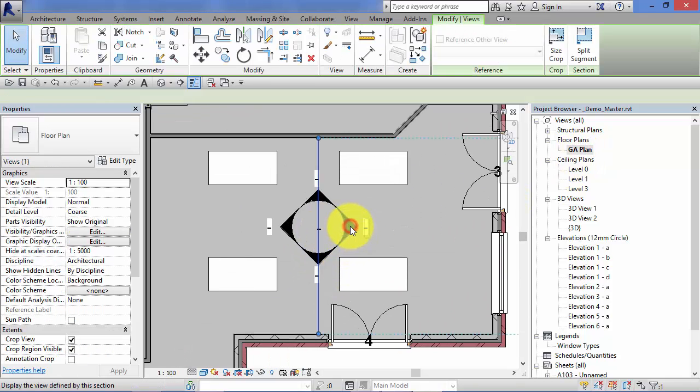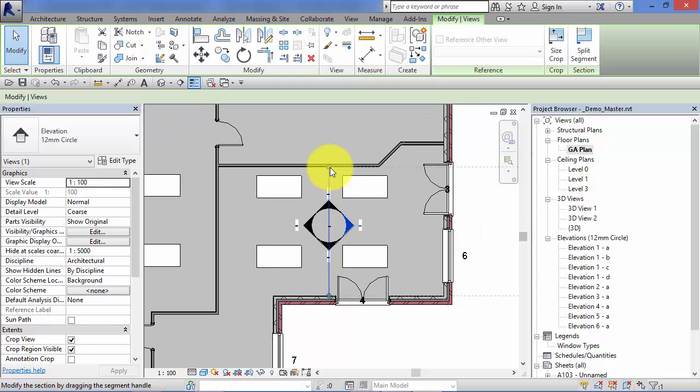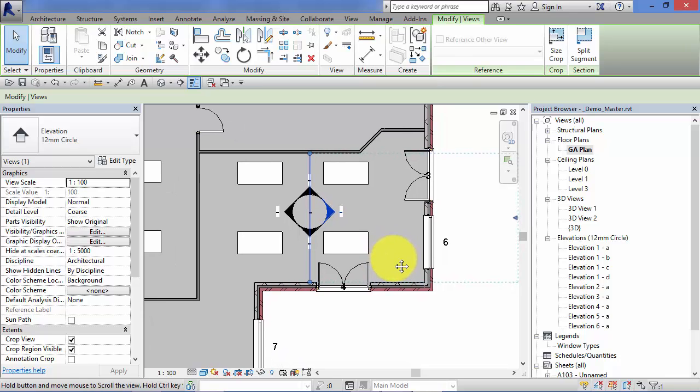Just going to highlight that particular view. Notice how the width of the elevation has been set automatically by Revit. Just watch out for scenarios like this. Obviously where the view was taken from, that was the width of the room. So strictly speaking, in that elevation, part of it is going to be missing there. So you either want to widen it there manually, or you're going to move the whole head down here, or have a separate marker to generate an elevation at the widest point would probably be the best solution.